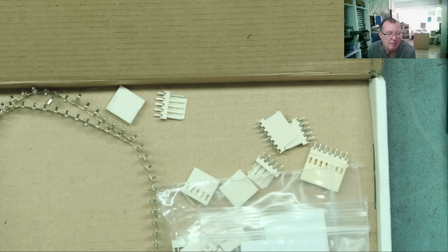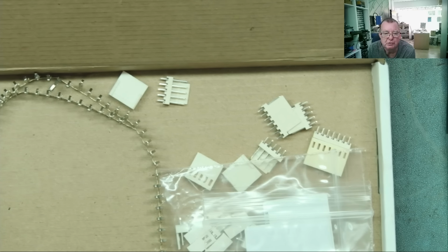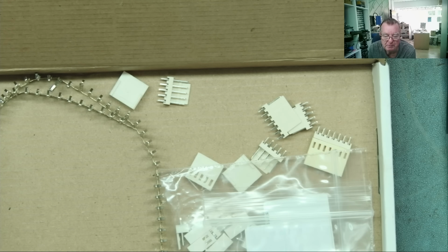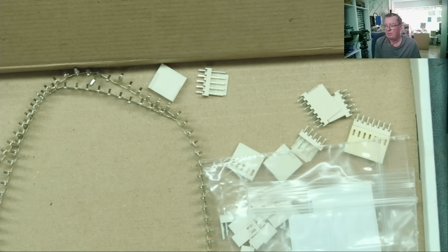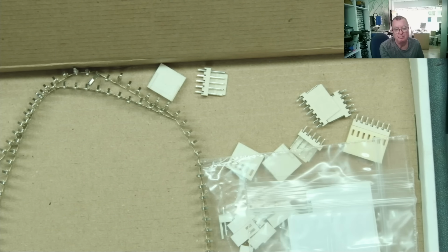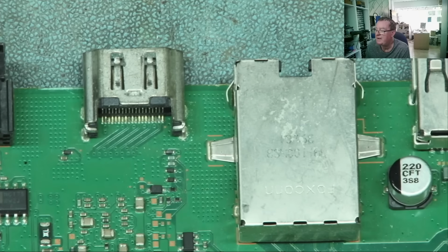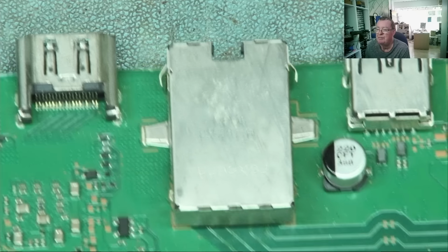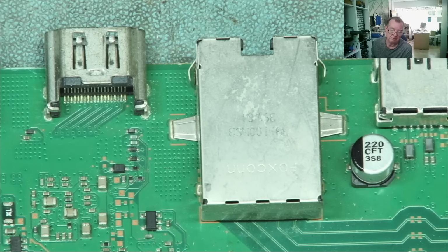Bear in mind that equipment is probably 40 years old these days that you're trying to work on, or they will fail just because you had to dismantle the equipment to repair another fault. So that, in my opinion, is how to deal with those and what to look out for. Connectors, a very, very common failure. Either the connector itself, the cable, or the connection to the board, the soldering.